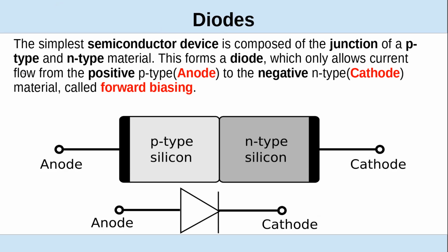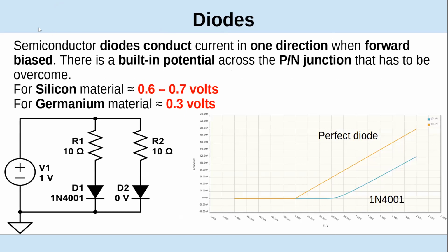There's another name for it, which I forgot at the moment. But typically it's from 0.6 to 0.7 volts for silicon diodes and 0.3 for germanium diodes. Most diodes that you're going to run into are silicon-based, so everything is going to be in the 0.6 range. I think one of the exam questions is 0.7 volts. Most everything says 0.6, but the answer key is always right.